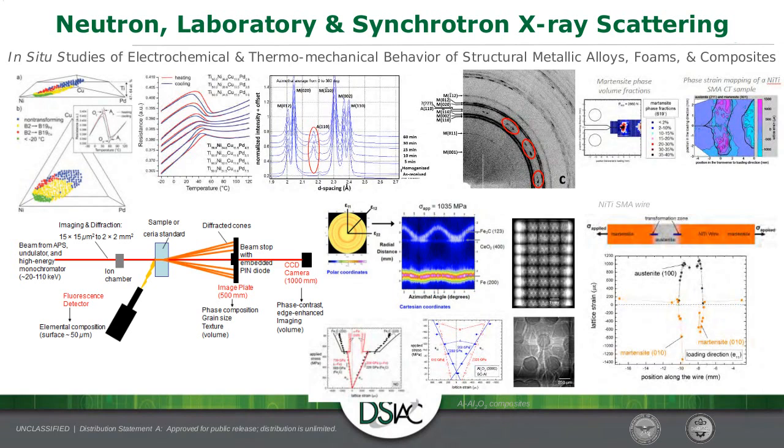Okay, so embedded SMA particles. On that question, there's a question here about what material system has been embedded with SMA particles. That's aluminum, so it's easier because aluminum is low temperature. I think the low temperature alloys are easier, to avoid having the material melt away. But that's something we could do. When I've looked at those, I think they work well, but they're a little tricky to do. I don't know that you'd necessarily want to do it on a large part, just because it would be costly, but maybe you would. It depends. But if you know where you're most concerned about stress, you might want to embed them there, and then you would have a way to non-destructively evaluate the part. As I mentioned, we can basically tune the stress to a certain level.